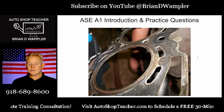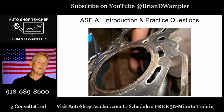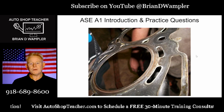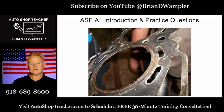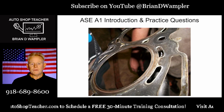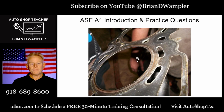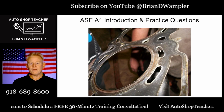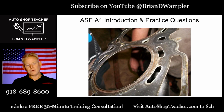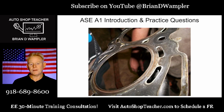Let's look at a head gasket here. You might be going into this test and maybe you haven't done a lot of internal engine work yet, but between the cylinder head and the engine block, we have what's typically referred to as the head gasket, where the two large surfaces are clamped together. And this large hole in the middle, of course, is for the piston to be able to come up into that area. And then along here, we have these passages that allow coolant to flow vertically alongside the cylinder and maybe even all the way into the cylinder head.